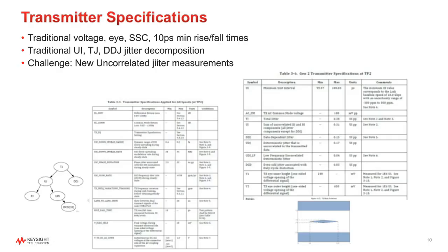As always, the receiver testing is much more complex. You have to test at the 10 and 20 gig rates. And for those who are doing Thunderbolt, there are 4 rates, which is 10, 10.3125, 20, 20.625. Then you have the no channel or short channel use case, and then the long channel use case. So lots of different cocktails to set up. This is going to be very complicated.